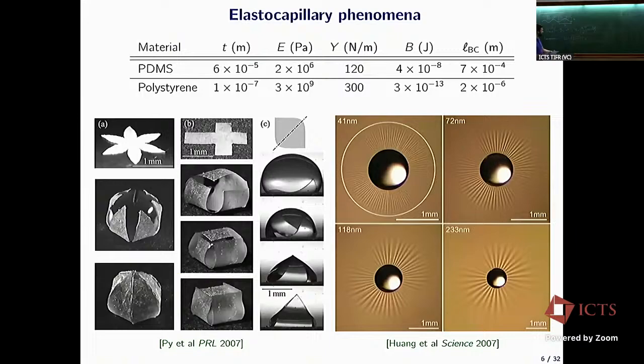Okay, if the end-to-end distance is L, the length of the plate is L naught. And so this is approximately, if I do a small slope expansion of the square root, L times 1 plus 1/2 the integral from 0 to L of zeta prime of s squared ds. L, yes, sorry.